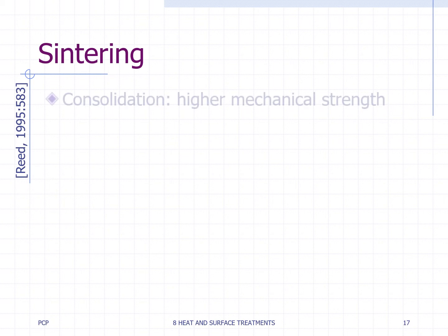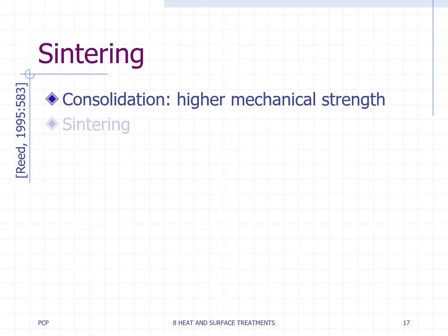Sintering is the term used to describe the consolidation of the product during firing. Consolidation implies that within the product, particles have joined together into an aggregate that has strength. The term sintering is often interpreted to imply that shrinkage and densification have occurred.